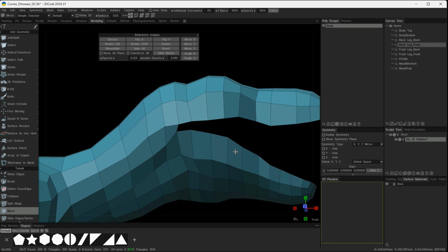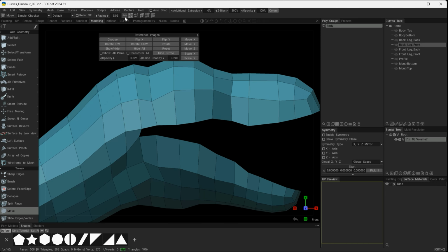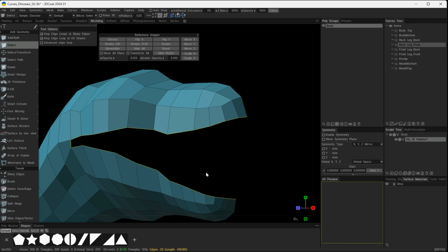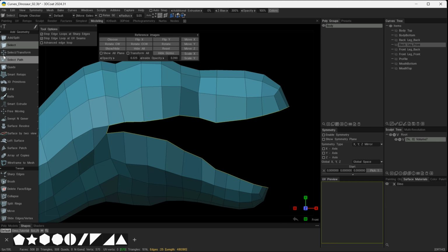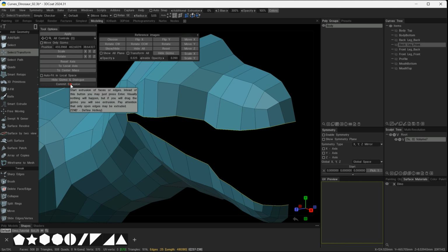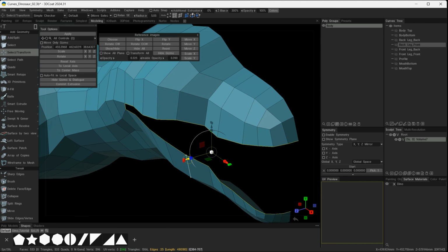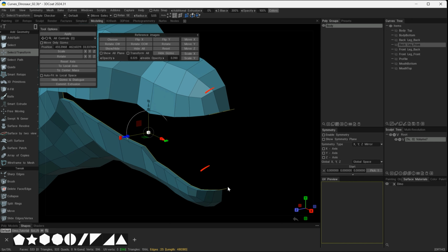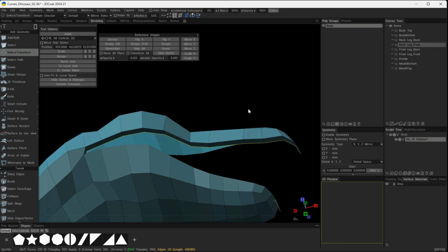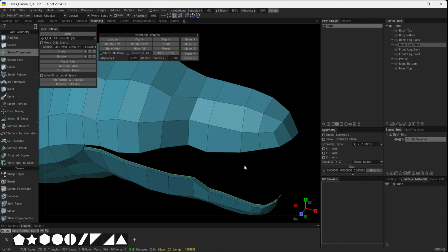And we will move all this around, but for now what I will do is select with edges. I will choose select edges. I'll choose this edge, and just double click in between to select everything in between those edges. And with that done, I'm going to use my select transform on here, and I'm just going to commit an extrusion and just push this inwards just to give that a little bit of thickness on there. Now you'll notice that on the front it's just slid these across, so we need to pull those ones in, but for now that's looking okay on the top and the bottom.